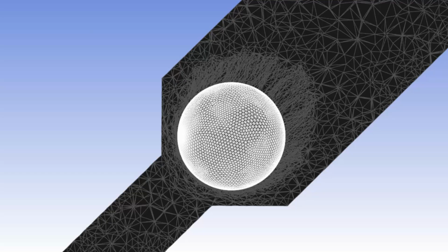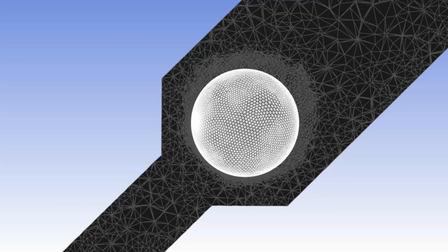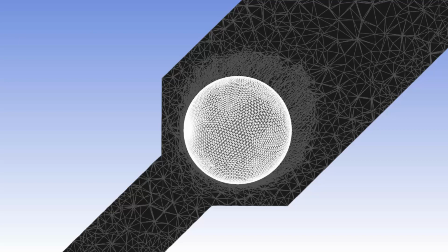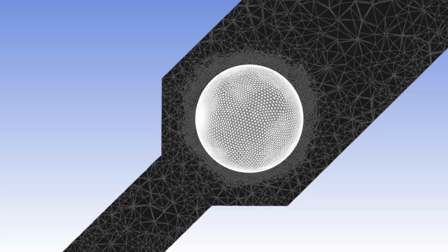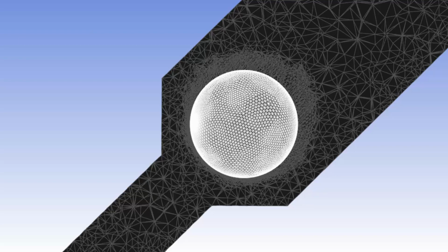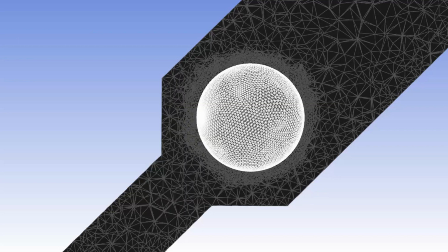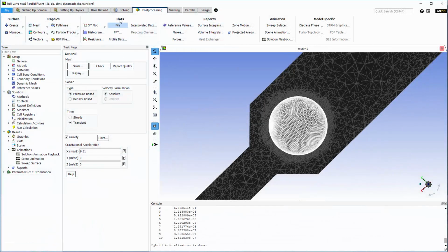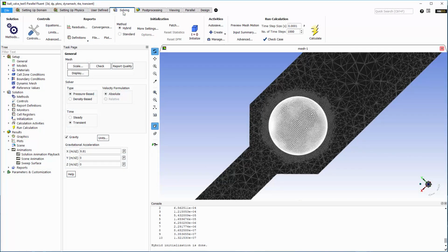Now that I've shown you how to create scenes, I'll cover the steps for creating a solution animation. One key thing to keep in mind is that you need to define solution animations after initializing the case, but before you begin iterating, so that Fluent captures the appropriate images during the calculation. This is why the Animation Definition dialog box is accessed through the Solving ribbon tab rather than the Post-processing tab.